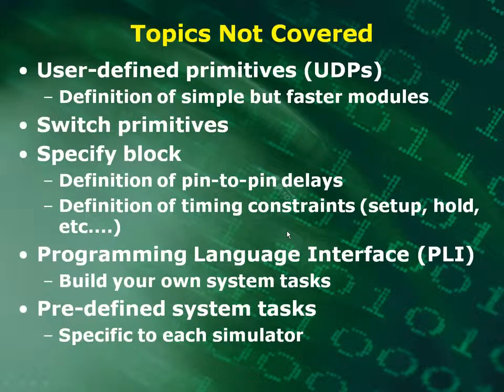Some of the topics I haven't covered in this class so far are user-defined primitives, switch primitives, the specify block, and a programming language interface, PLI, so where you can build your own system tasks if you like, and predefined system tasks, which are specific to each simulator. I also haven't discussed some of the newer Verilog 2001 things, such as say the generate statements. We'll take a look at that right after this lecture.